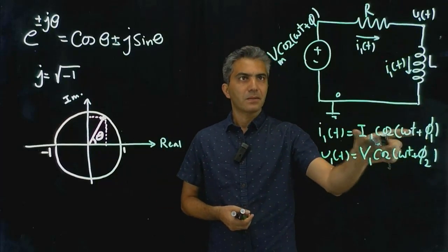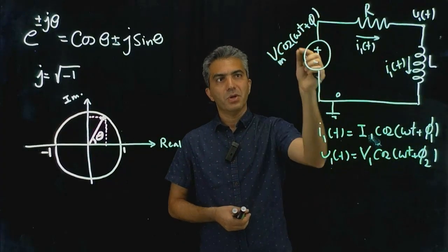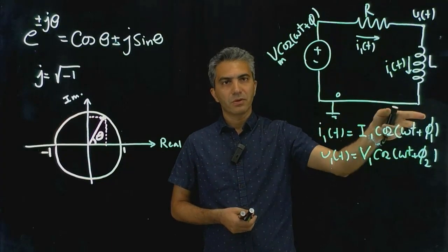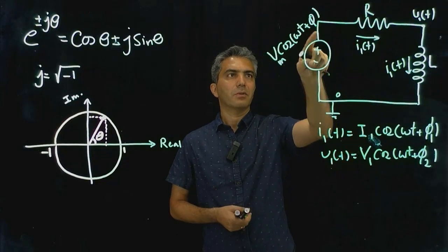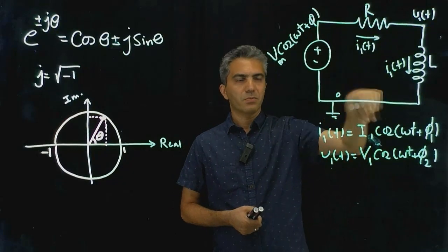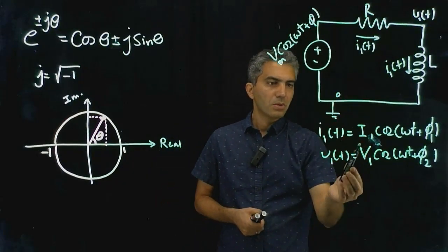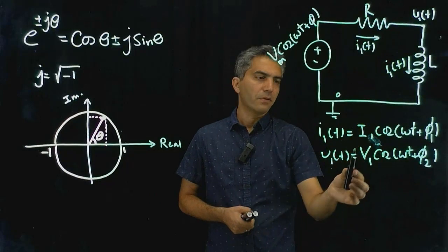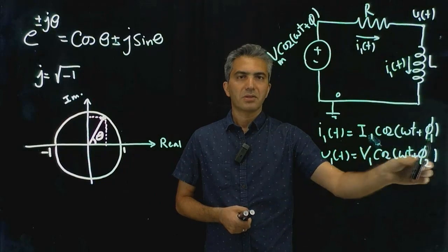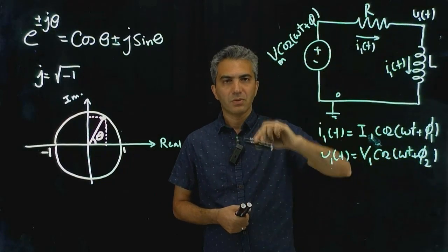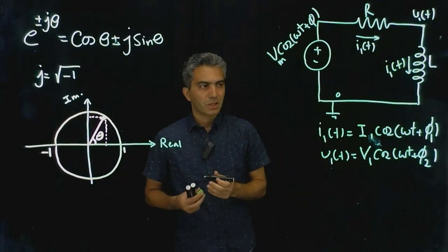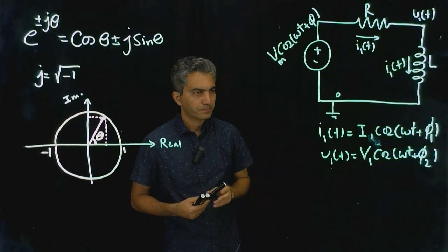And this just follows that format, as you can see. What's going to change is the amplitude of the signal that we're looking for, and these are the only two signals: there's a voltage here, a voltage there for the two nodes, with ground assumed, and there's one current going into this loop. So any signal in that circuit is going to have this same format: an amplitude, a sinusoidal function with a frequency that matches the frequency of the input, and a phase that may or may not be different from the input, depending on the circuit.